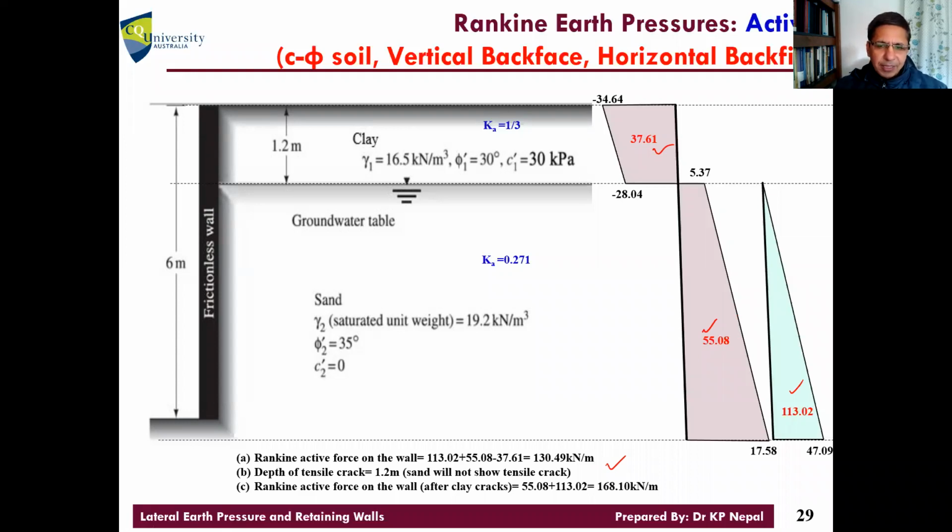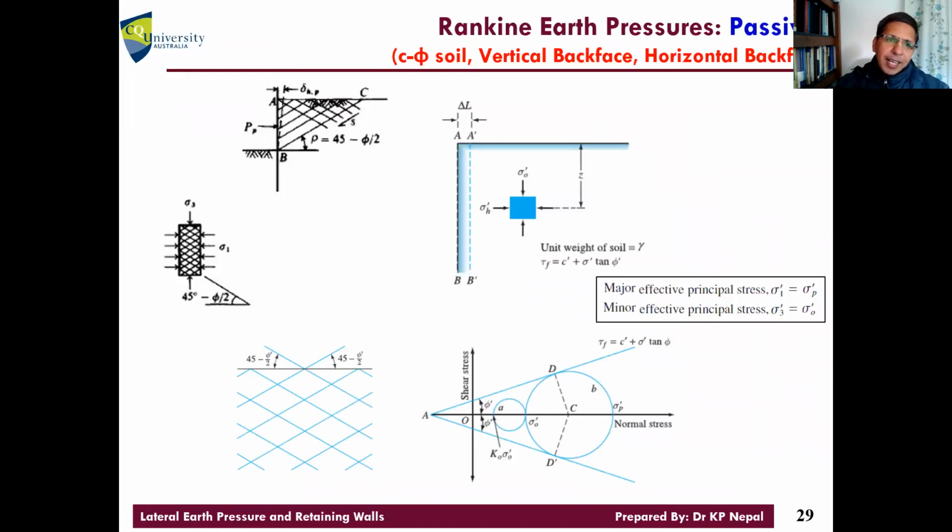All right. Okay. Let's go next. So now, until now, we covered the active case. Now we'll go to the passive force. Exactly the same concept. The only difference is the failure plane is different. That's why we have slightly different equations. So the passive case. Passive means the wall moves towards the backfill.